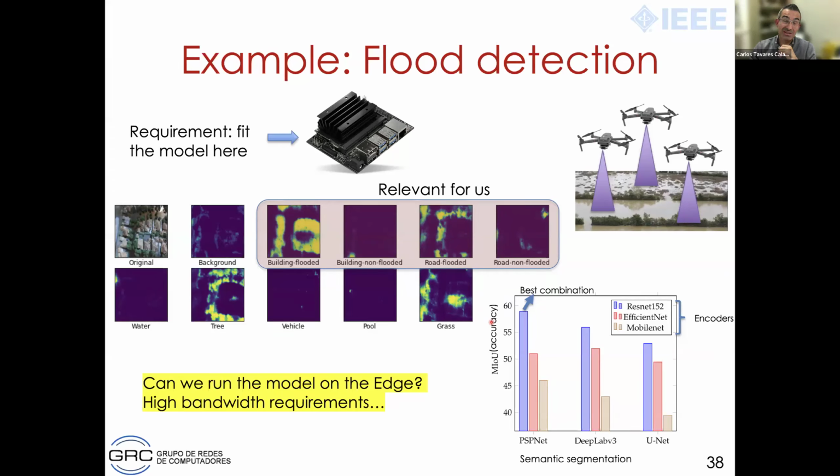So right now, UAV security. When you're thinking about it as a flying IoT device, and you are thinking about an attacker that wants somehow to intercept communications or take over communications, the problem that we have compared to standard IoT devices is that we have possibly many open channels. For example, in the drones that we use, you have the remote control channel, and then you have the telemetry channel. And then we are adding our own wireless channels. In terms of wireless channels, maybe you have cellular communications via 5G, and then you have some ad hoc communications for UAVs to talk to each other. So by having more open possibilities for attacks, the attack front is wider. So immediately that makes it more prone to suffer from cyber attacks.